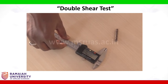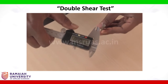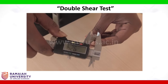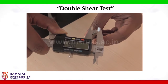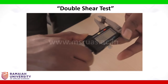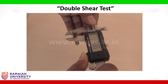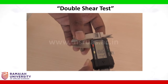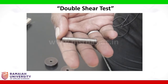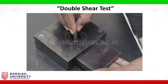To begin the experiment, first we need to take the diameter of the given specimen through the vernier calipers. The diameter of the specimen is 7.8 mm. After taking the diameter of the specimen, we have to fix the specimen into the shear box.